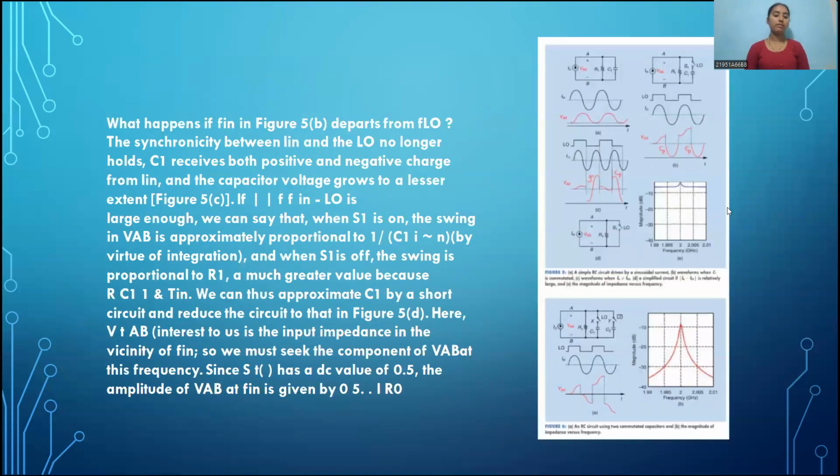What happens if fin in Figure 5b departs from fLO? The synchronicity between Iin and the LO no longer holds. C1 receives both positive and negative charge from Iin, and the capacitor voltage does not grow to a large extent.